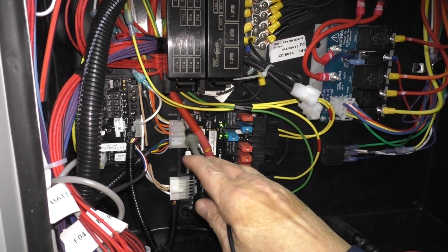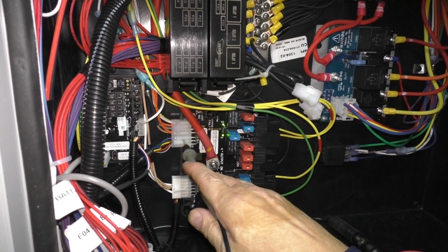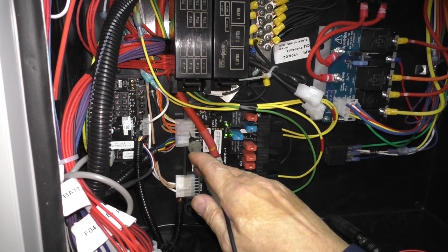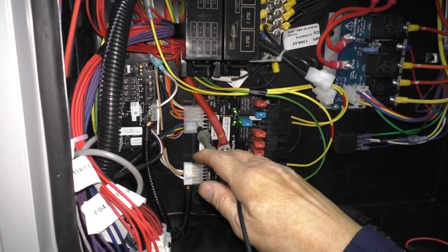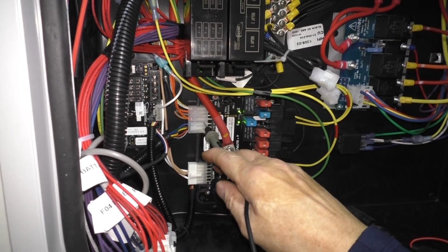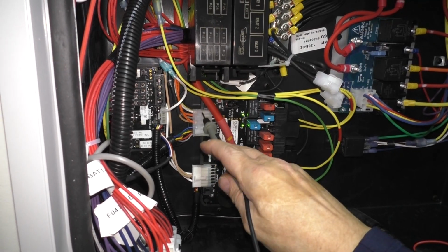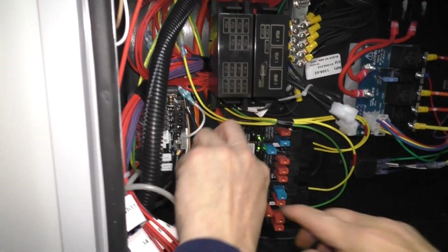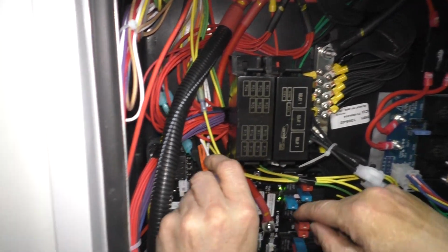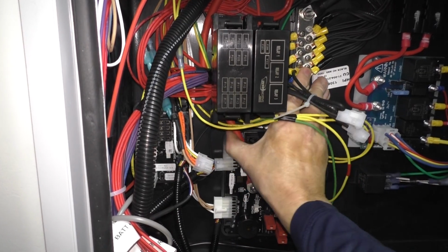The PRPC's low current outputs are not physically fused. They're smart transistors, so they have self-protection. These are all rated at 0.5 amp. If there's a short on the output or the load current is too high, that output will shut off automatically. Once a fault is detected, that output stays off for at least 5 seconds, and then it will retry. If you unplug the load from the 8-pin connector on the lower left of the PRPC, then wait 5 seconds, that output should come back on.